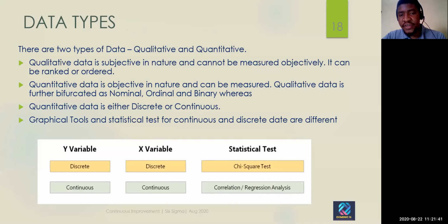What data are you trying to collect? If you're trying to collect how aligned your labels are, then you are looking at attribute data. So I'm checking, how many aligned labels do I have? If I'm trying to check weight values, then I'm looking at quantitative data. Maybe we lose 6 grams or 10 kg from every product that we produce. That's a waste. That's a place that we need to measure.